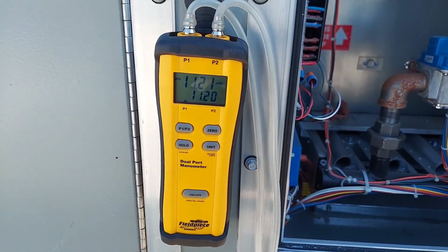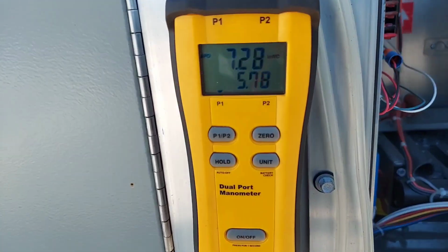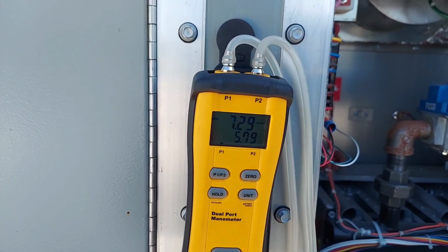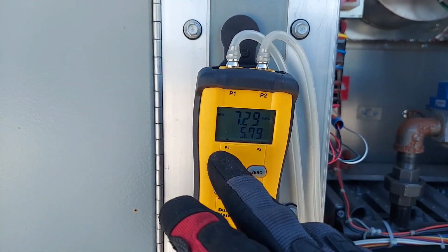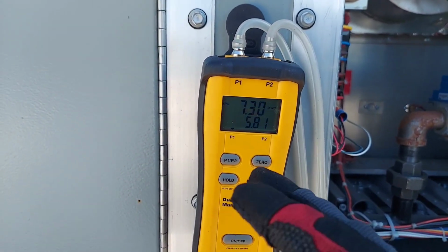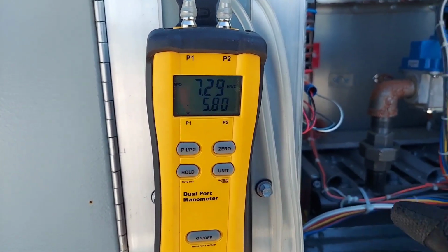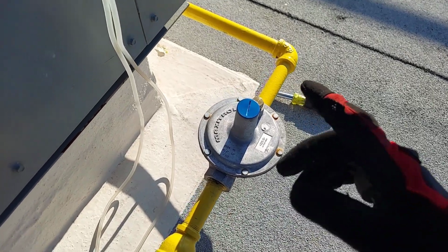Oh, this spiked up. See? There was a bit of a spike. You see that initially when I opened the valve, the PRV spiked. But we're back down now. You can see we are at 7.2, and that seems a little bit lower than what I said. So again, that's the reason why you don't want to have your PRV set up to the minimum.